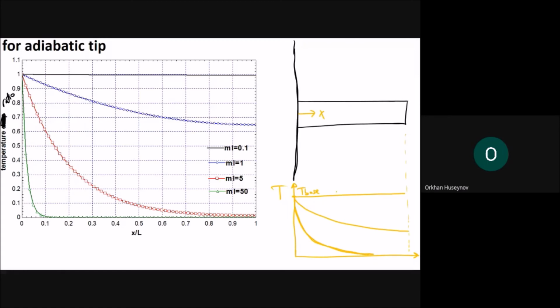Okay, the temperature of the base, and the first one that is given here is the ideal fin. And this one is not good. Why is the first one the ideal fin? Because it has the maximum conductivity, or the K. You can see that if the temperature here is 75 degrees Celsius, it is 75 degrees Celsius here, 75 degrees Celsius, 75 degrees Celsius. You can see that the conductivity information is propagated very fast. The temperature everywhere is 75 degrees Celsius. What it means is that K is very large. K is infinite. Okay, but if you look at the bad case where the temperature variation drops suddenly.